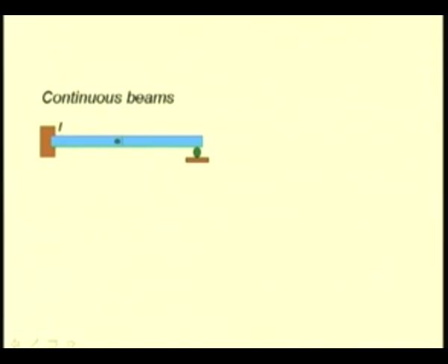Let us designate these points as A, B and C. Here we see 2 beams are pinned at B, and the beam BC is supported by a roller at C, and the beam AB is cantilevered at A, that means fixed at A. So, let us draw the free body diagram, and in order to develop the equilibrium equations, we have to dismember it as 2 members AB and BC,